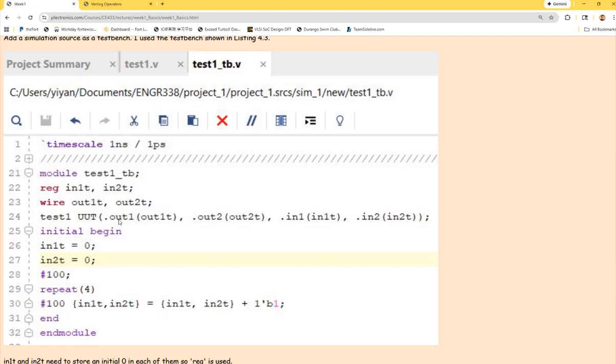So we are looking at the example on problem number 6. You can see dot A. We don't have the half adder module included over here, but we do instantiate it in the top module of this example for problem number 6. You'll see a line break between the different lines. There's a dot A, input underscore A, comma, dot B, input underscore B. Doing it this way makes it super clear which ports are being connected to the top.